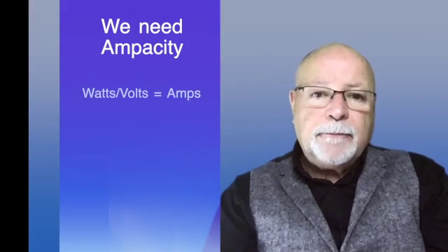When a manufacturer builds a piece of equipment, they add all the minor totals up and they assign a wattage. In other words, that's the total amount of energy of all the processes that electricity will perform. And it will give a value to that piece of equipment. It requires 1,500 watts. But in the electrical community, when we install equipment, we convert that to ampacity. So we'll take and use a formula to do that.